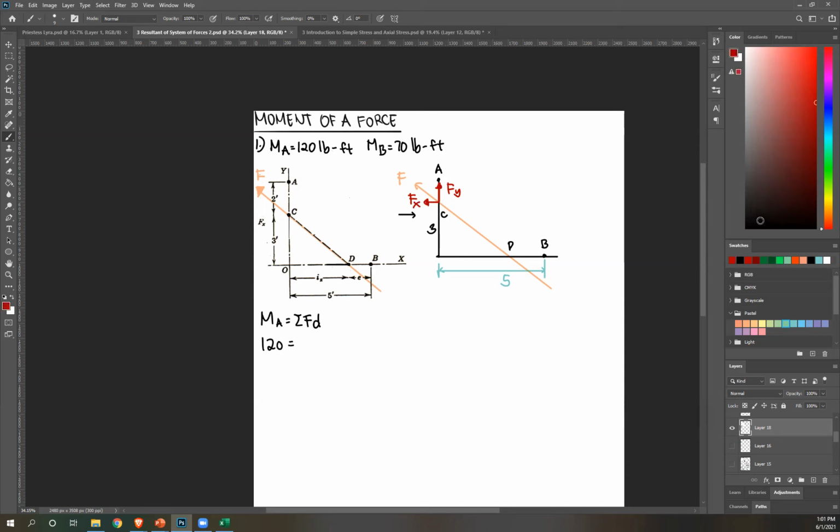Okay, so write out our equation going back here. This is your F. Let's start with Fx. First thing to know is the sign. So rotate Fx about point A, since again we're taking moment about A. That's clockwise, therefore positive. So positive Fx, and then multiplying it by the perpendicular distance.